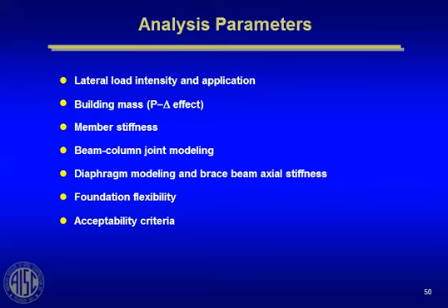and braced beam. When I say braced beam, I'm talking about the beam that's part of a chevron bracing system or an X-brace system. Some real gotchas out there that we're going to talk about when you design brace beams. Foundation flexibility. Many engineers take the easy way out and say, I'm going to assume the base of my foundation is pinned.